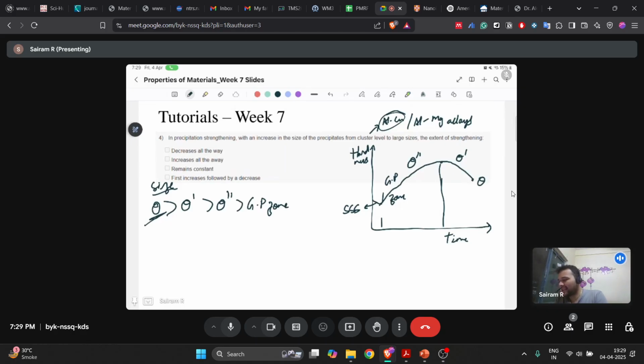Again, the reasoning behind why this happens is also explained in this class. Say in a grain, there are small precipitates forming. For the dislocation to move in its plane, when it meets a precipitate, to a certain extent it is going to shear this precipitate away.